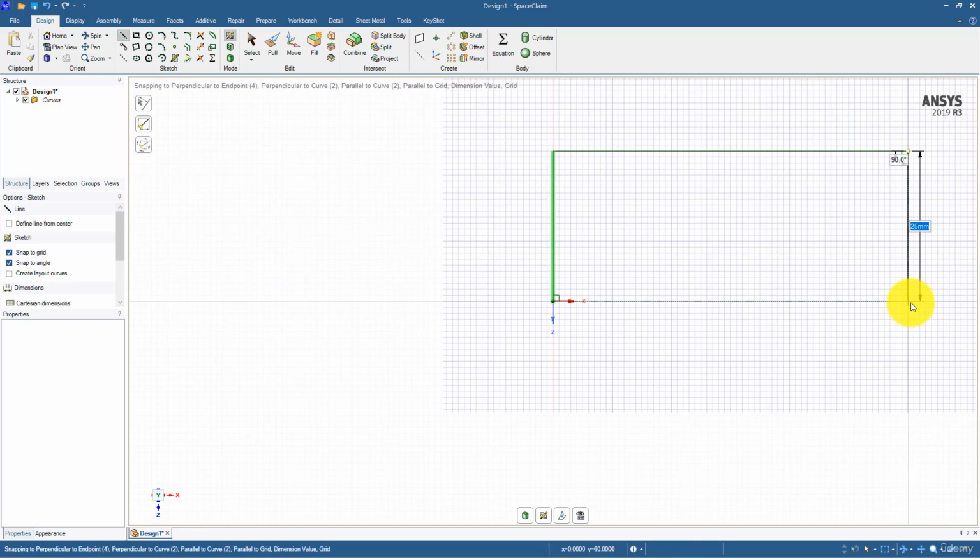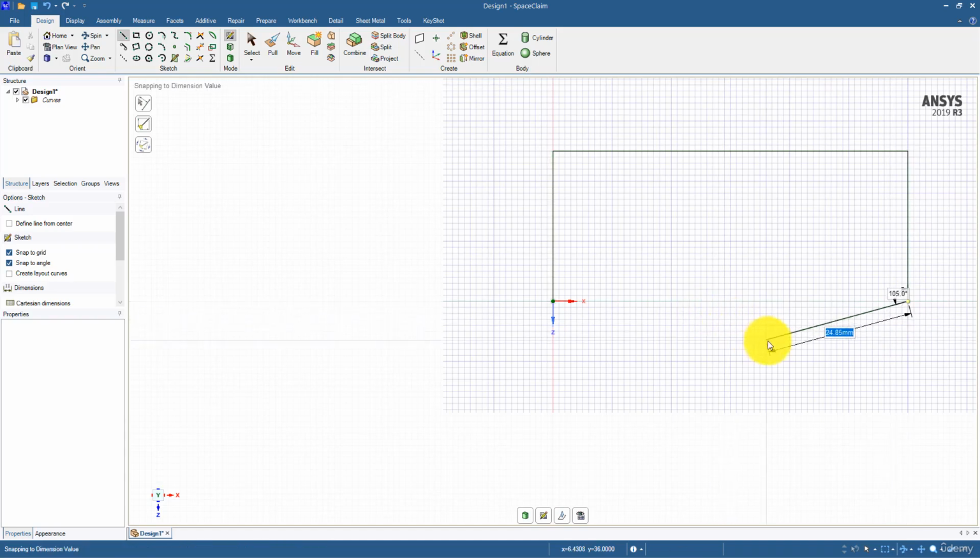Then complete the sketch by making another line vertically dropping onto the axis. If you just revolve this line, basically this will only make one surface, and you have to close the two sides with the help of the Fill command, or create these faces with the Blend command. If you revolve these three lines, this will make a solid body in one command.